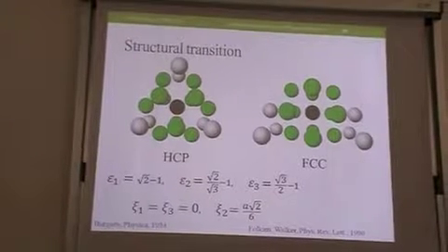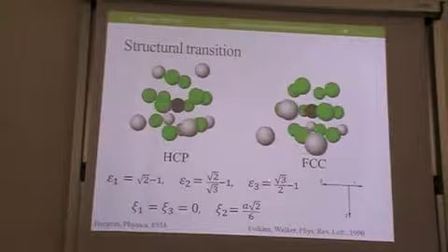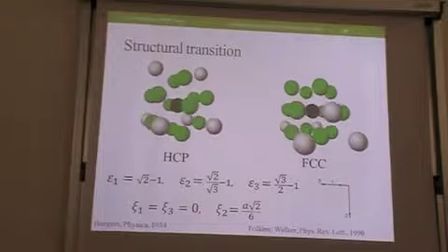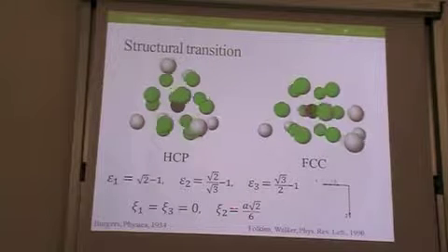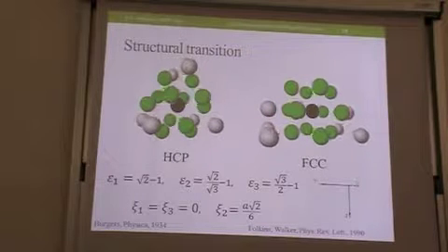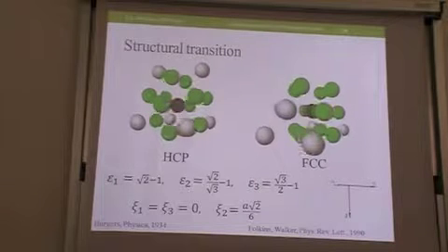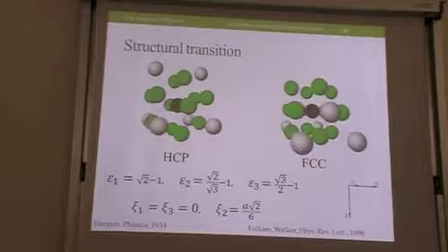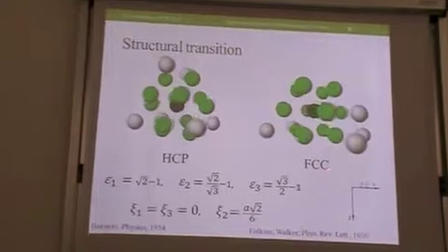So, doing some geometry, we understood that somewhere in the center of the second zone, we have a stress-free FCC, and that's its coordinates, and that's the corresponding sublattice shift. I hope you understand where everything is turning. So it's axis number 2, and axes 1 and 3 are turning. And the green spheres are the first coordination spheres of HCP and FCC respectively.